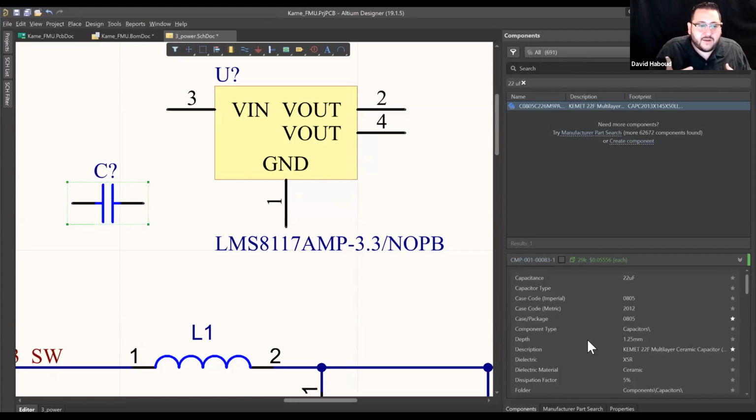So you get the benefits like you would of a popcorn / generic component without the downside of potentially mislabeling something, putting the wrong parameter, forgetting to change 10K to 100 and having 500 boards that don't work, right? So it's a very powerful addition that I think is pretty great to have.